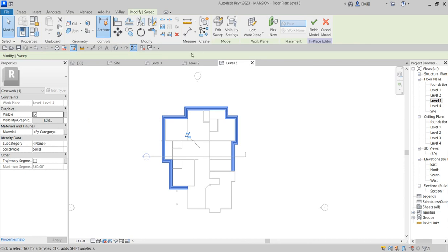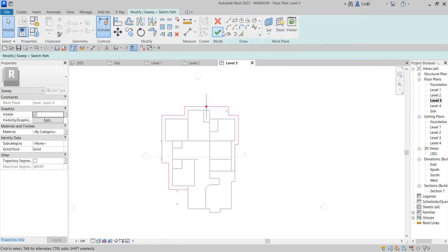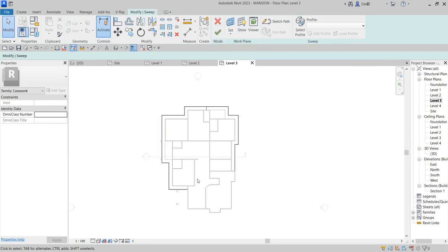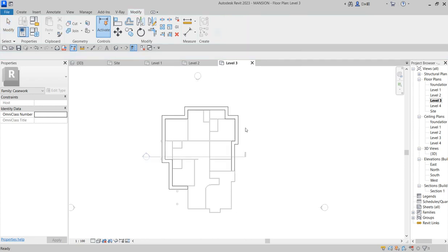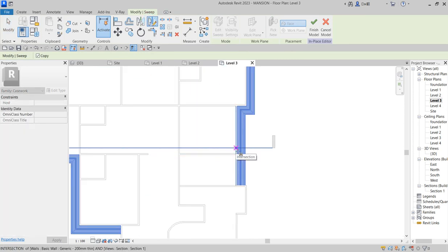So as you've done this one now, what you do next is that you mirror. Okay, wait, let's edit and see where the plane references is. So here we are going to do mirror for that, and we are having the three places because this side has already joined together. Another one is going to create itself around here and another one around here. So what we do, click finish, then here you do mirror. Now click on mirror.